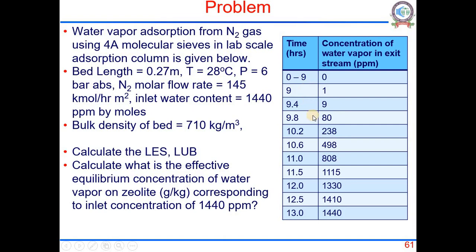This is the data of breakthrough. From 0 to 9 hours, no water vapor is in the exit, everything is getting adsorbed. At 9 hours, 1 ppm, at 9.4 hours, 9 ppm, and so on. You can see that after 13 hours the bed is completely exhausted. Whatever is the inlet concentration, everything is coming out of the bed. So try this problem yourselves, and once you have completed, you can see the solution. Pause the video and try this problem yourself.